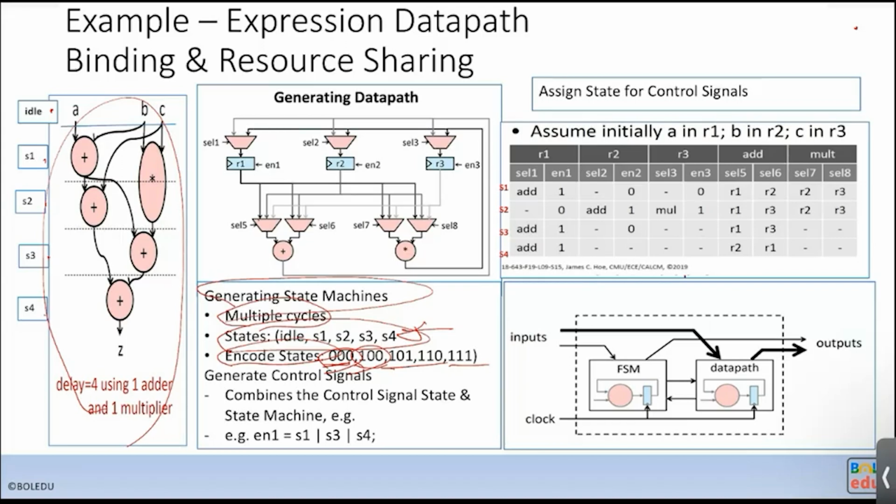That means for one state to the next state, if you have a multi-bit transition, due to the delay of the different bits, you will generate glitch. Sometimes glitch does not matter because it's a synchronous design, but if you want to use a combination of the state to control something, and that control signal creates a glitch, it's not good.